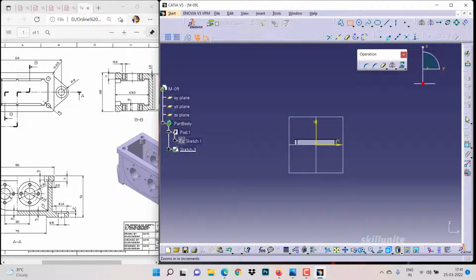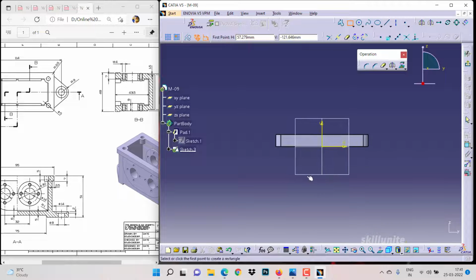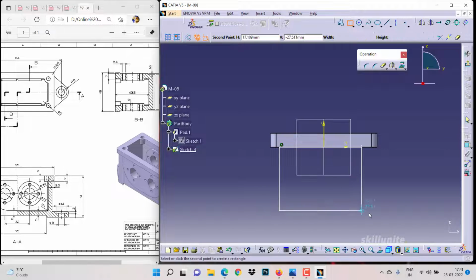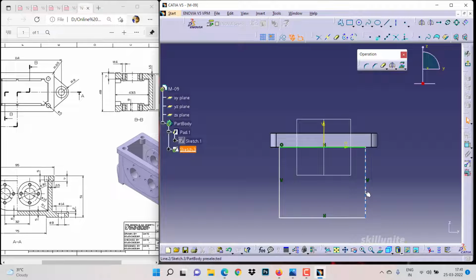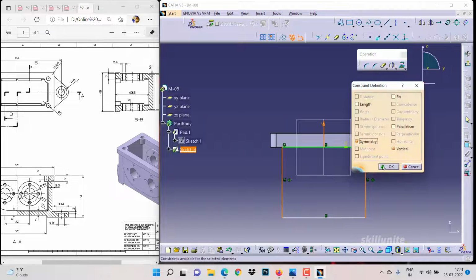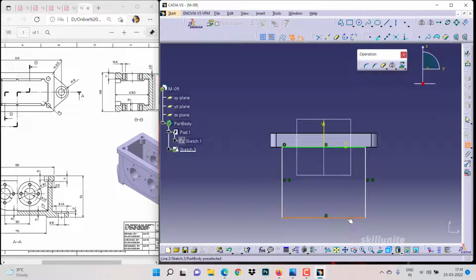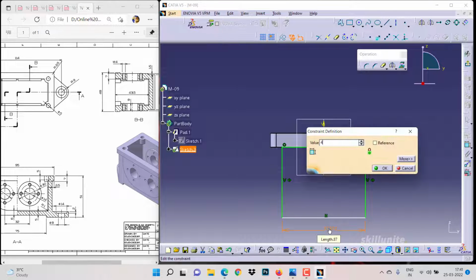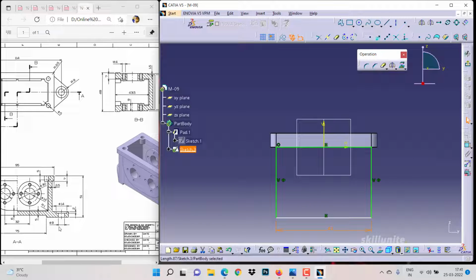The rectangle we are making is going to be 43 mm wide. That has to be coincident over here, and they need to be symmetrical first, so we will make that. Then keep the width we know, 43, that we have already given. Then this distance we have is 51, from the top to the bottom part, 51. Then click on exit sketch.